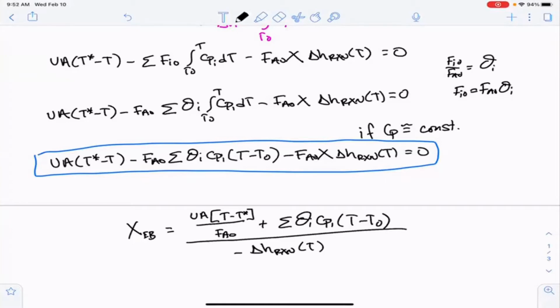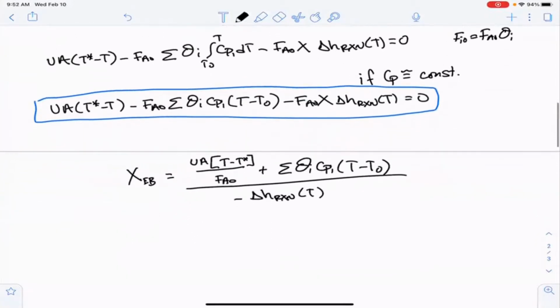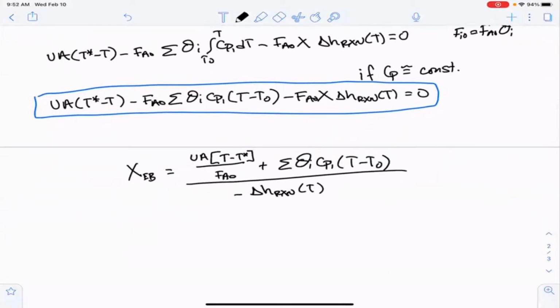The other thing we could also do is solve for the temperature explicitly, because if you remember last time, we ended up with an expression that T equaled T0 plus essentially the reaction term. If you want something that looks very similar to that, you can solve for it. You do that by foiling this expression out to get those terms related to our reactor temperature at the end.